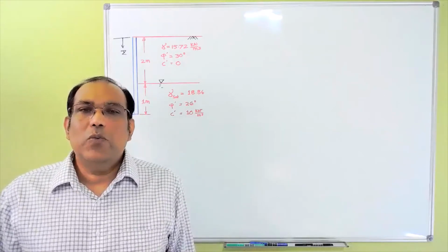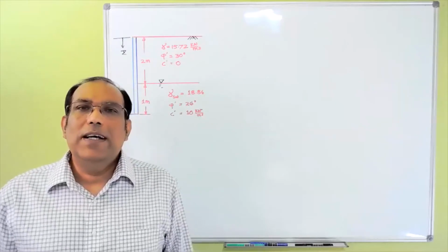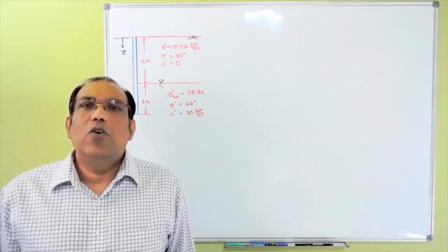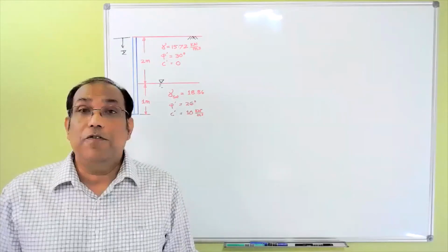Okay, so once you have to do the Coulomb's method, then basically we have to know what is the friction between the soil and the wall. Okay, so here actually they gave you this value like your delta prime is actually half of your phi. I'm just putting the value here. You can just check that one in the spreadsheet. Okay, so here your Kp